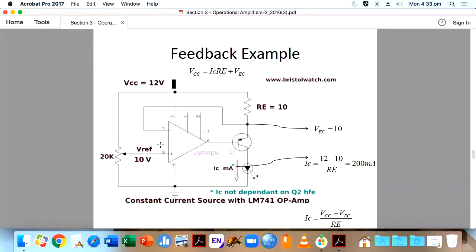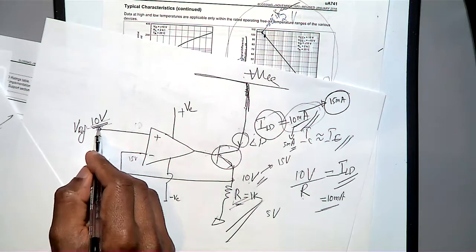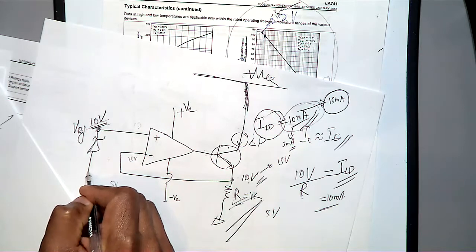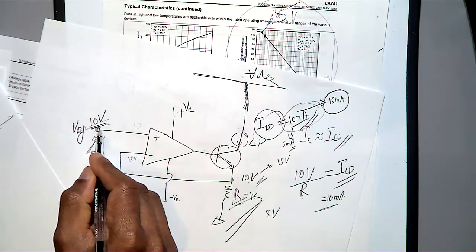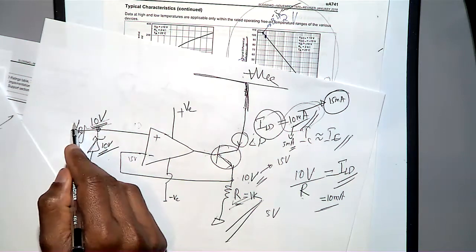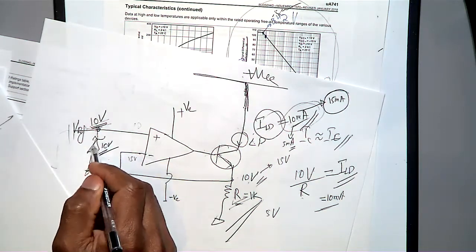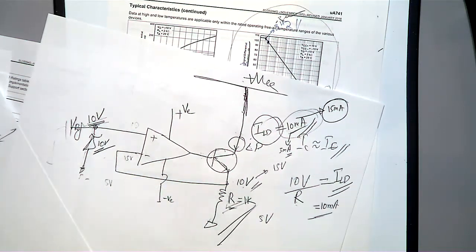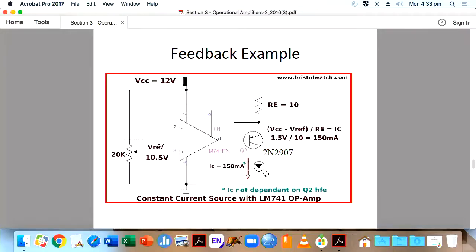When you come to my drawing, here this voltage we are setting, because this voltage is a crucial one. So here maybe you can put a Zener diode, rated to 10 volt, and then from here you can connect a voltage source, so that this is 10 volt always. So I think this much understanding is sufficient for designing circuits using op amps.